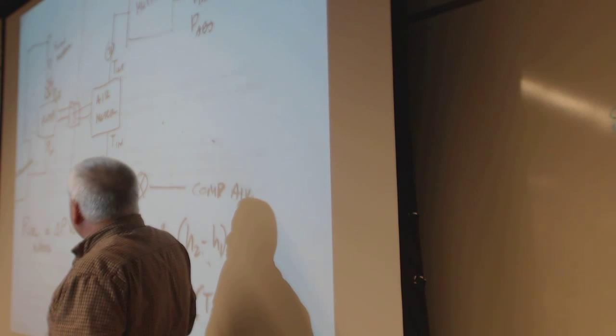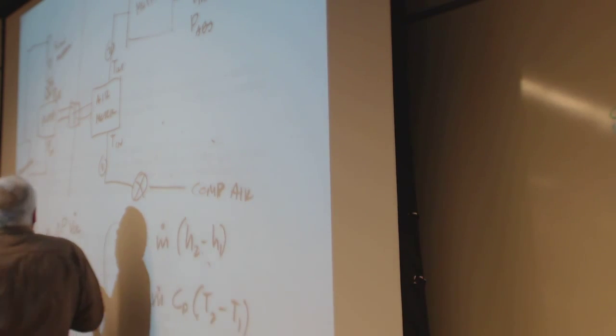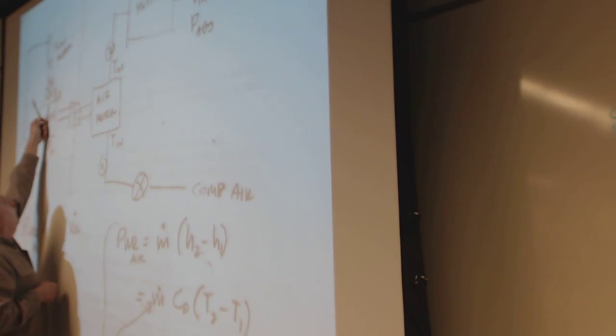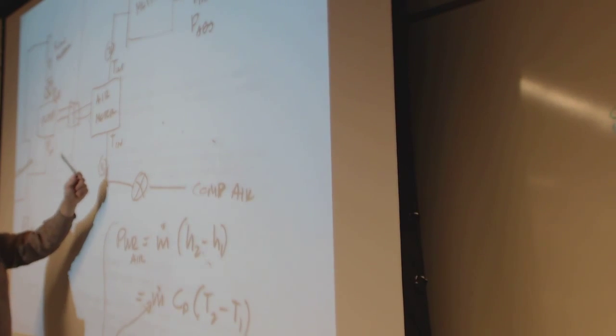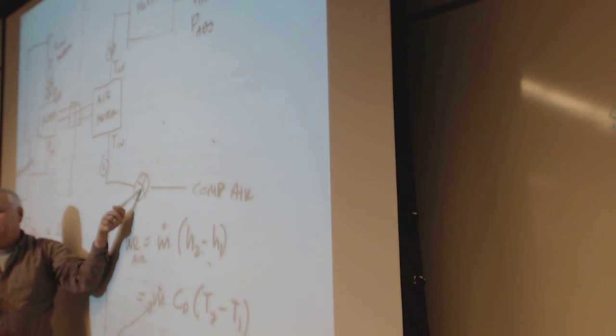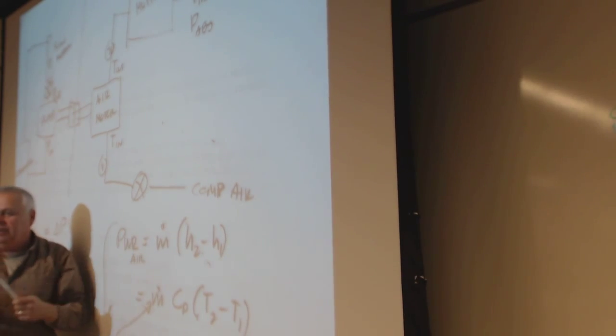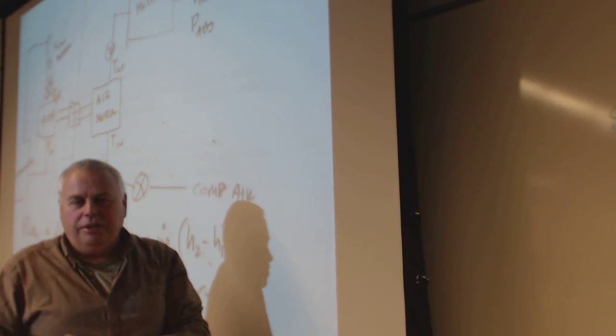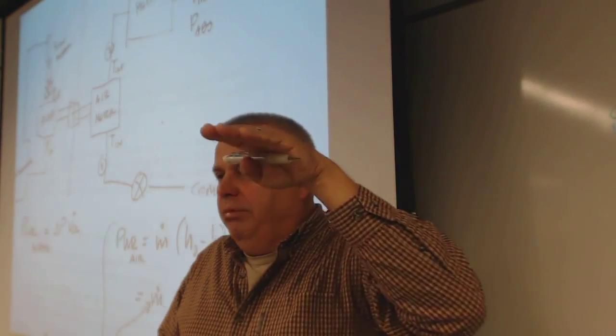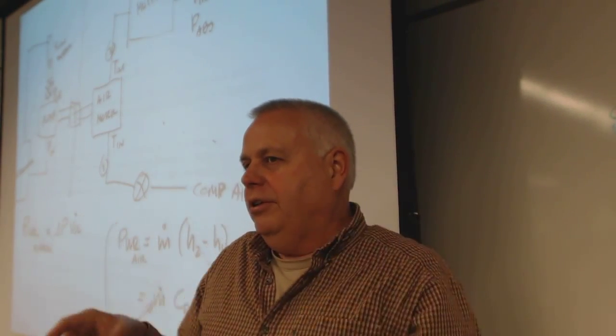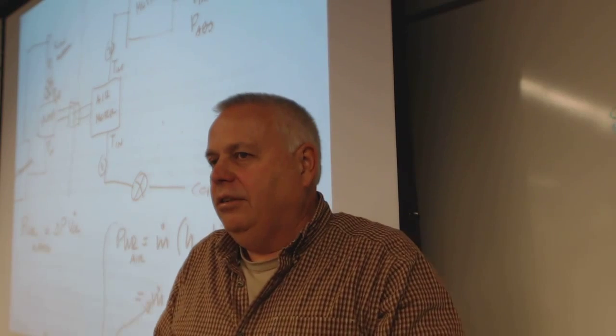So we're creating a load with the output valve. We're giving it more power with the air valve. And it can be pretty tricky to try and hit both the pressure outlet and the RPM you're going for and wait for it to settle.